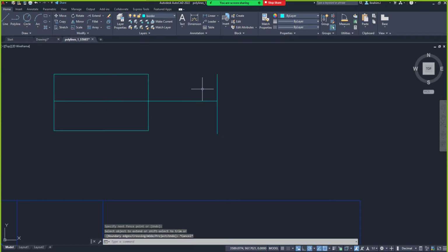So now, another thing is that your extend tool works only on a straight line. It will not bend. If I have a line like this, if I have a circle around here, or if I have another line like this, and I want this line to come and bend to touch this line, it will not work. Are you with me? It will not work that way. So your lengthening just works in 90 degrees, if it's completely horizontal or completely vertical or diagonal as well. Are you with me?